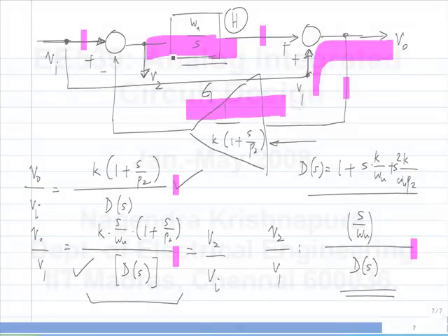If you want to manipulate the poles, you have to change something in the loop. Okay, is this okay? So to manipulate the zeros, you don't have to do anything to the loop itself. Okay. So this definitely you should keep in mind, and when you get answers and so on, maybe in some particular case you are required to analyze different transfer functions in a loop. You have to get them to have the same poles.